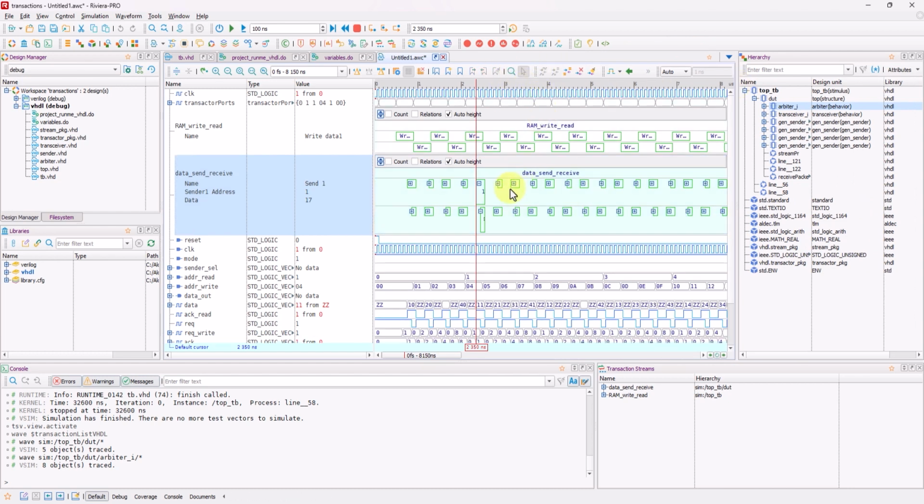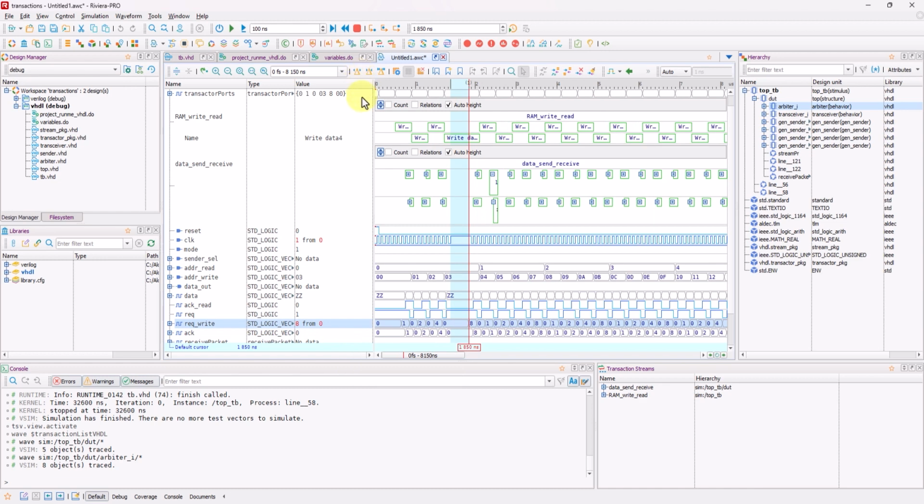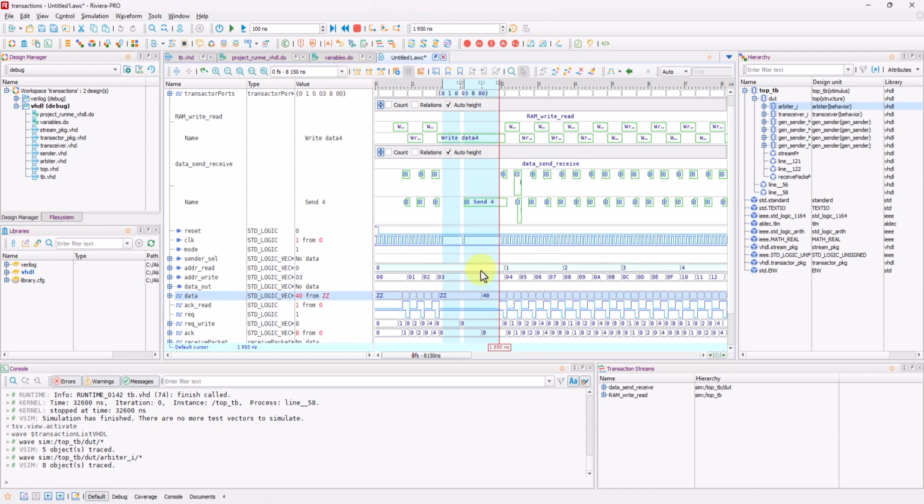In this waveform viewer, you can also take a look at the delta cycles of the signals. To do this, click on an area of an event of the signal and then click on Open Delta. Even though the simulation views the change as instantaneous, you could see at the top where the timescale is that the change occurs at this many nanoseconds plus 1 delta cycle. You can open up the view of multiple delta cycles by repeating the previous steps mentioned.